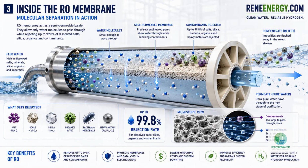Image 3 takes us inside the RO membrane. This is where the science becomes visible. The membrane acts as a semi-permeable barrier. Water molecules are small enough to pass through, but salts, silica, bacteria, organics, and heavy metals are rejected. The visual shows feed water entering on one side, pure water passing through the membrane, and contaminants being flushed away through the concentrate stream. This is not ordinary mechanical filtration.